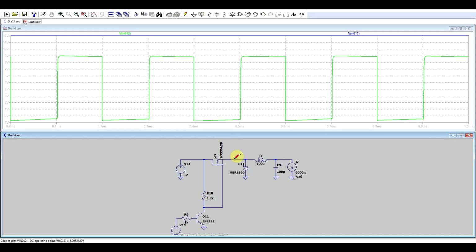So the voltage in its source will be 3 volts lower than the voltage in the gate, and the voltage in the gate at the moment has a maximum of the supply voltage. So the only way to get this thing to have a higher voltage in the switching node, so to have a very small voltage drop on the transistor, would be to drive the gate with a higher voltage than the input supply voltage. So if I'm supplying the circuit at 12 volts, I will need 15 or 20 volts or something that is more than 12, more by the gate threshold voltage at least.